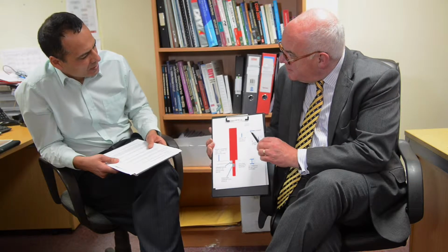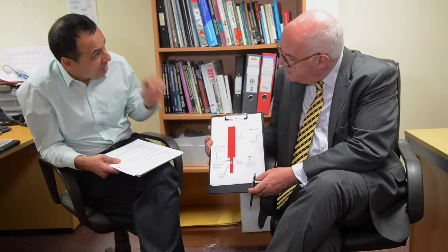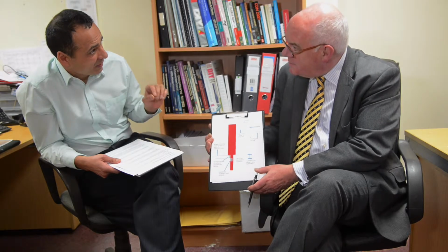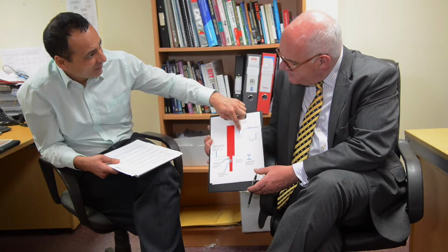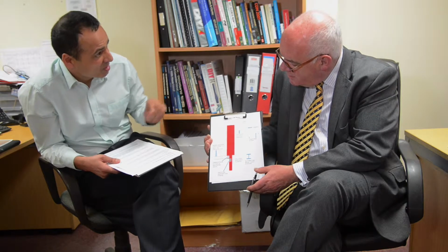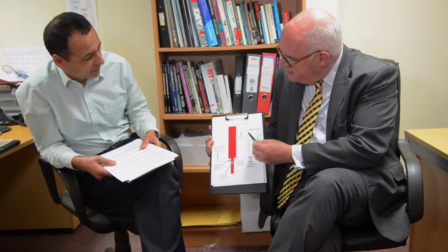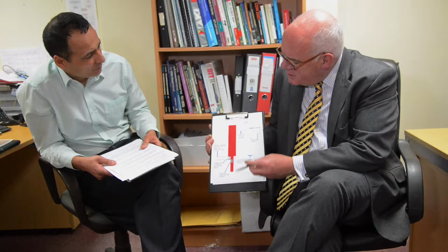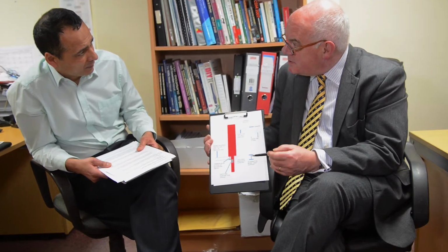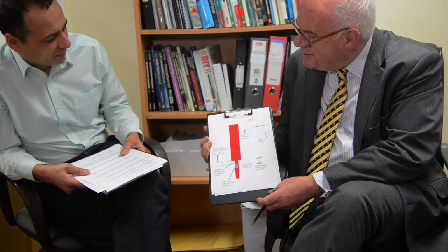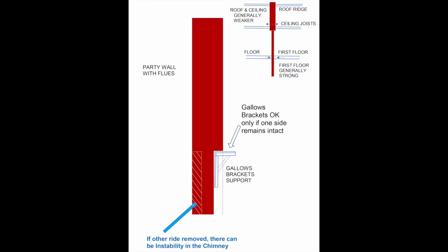Right. So it is very important to dry pack the gap between the supporting steel channel and the bottom of the chimney breast wall. Yes, that's right. The spans here are relatively short, so you don't need to worry quite so much about deflection as you might in a larger floor opening. So ordinary dry pack, properly rammed in place, will do the job. Okay, wonderful.